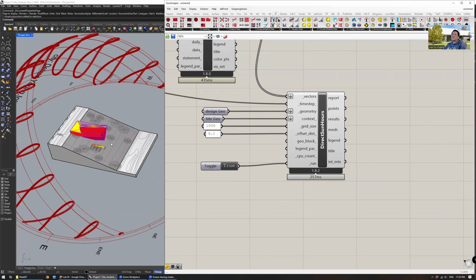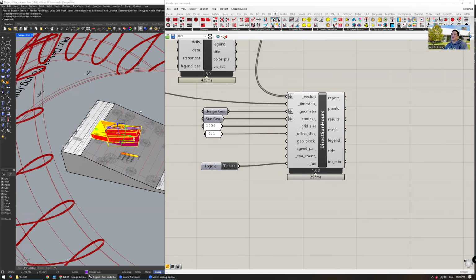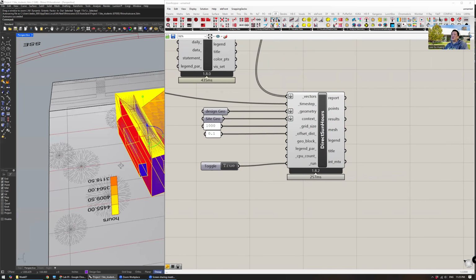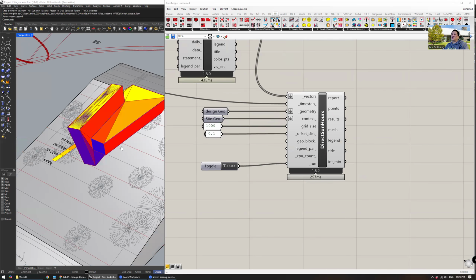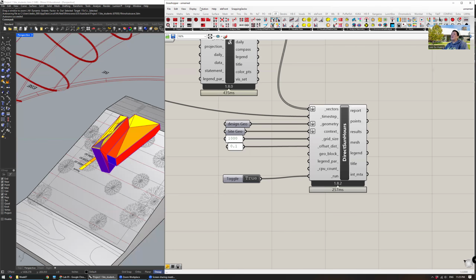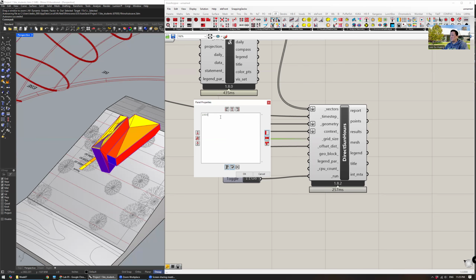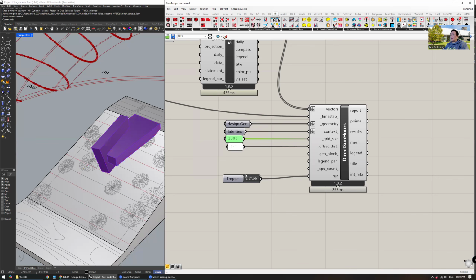So this popped in right away, which tells me that especially in this case, my grid size is really large, right? And again, if you're not seeing the display, display preview mesh edges basically hides and shows that. So let's bring this down to 100. Say okay.